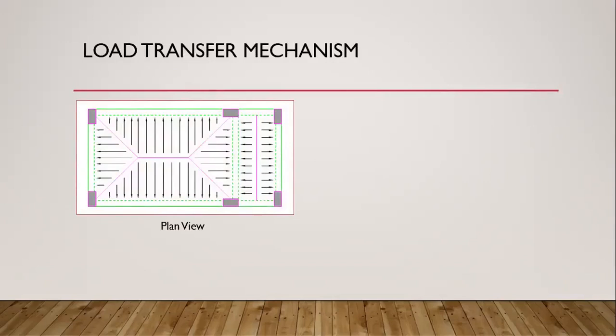That's why it is called as one-way slab, and in two-way slab, the spanning direction is in two directions. Therefore, it is called as two-way slab. And then finally, the reaction from the beam gets transferred to the column and then column to foundation.